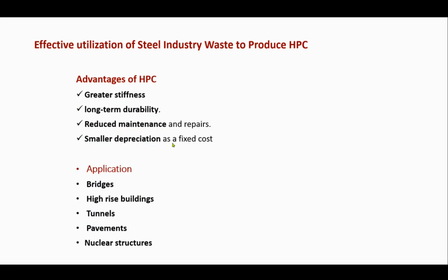Okay, in M30 grade, after 28 days the concrete cube strength should be 30 megapascal. So whatever grade there is, like M20, M30, M40, M50, M60, M70, M80, M100, these are the different concrete grades. M represents mixture, and 20, 30, 40, 50 represent the strength in megapascal after 28 days. Okay.